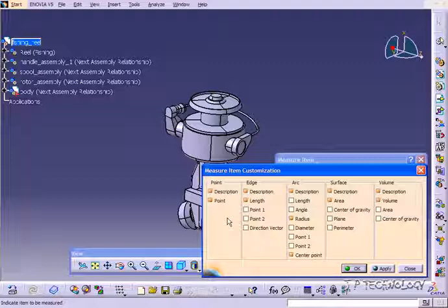Because you're also able to choose a part and faces by itself, you're going to be able to take the surface and the volume, and you're also able to get dimensions for those too. So when you select an object, it's going to take whatever is viable for it. If you choose a line, it's not going to tell you the area because there's not going to be any area to the line. It'll just tell you the length. So you're able to change any of these if you want to. For now, just leave it alone.